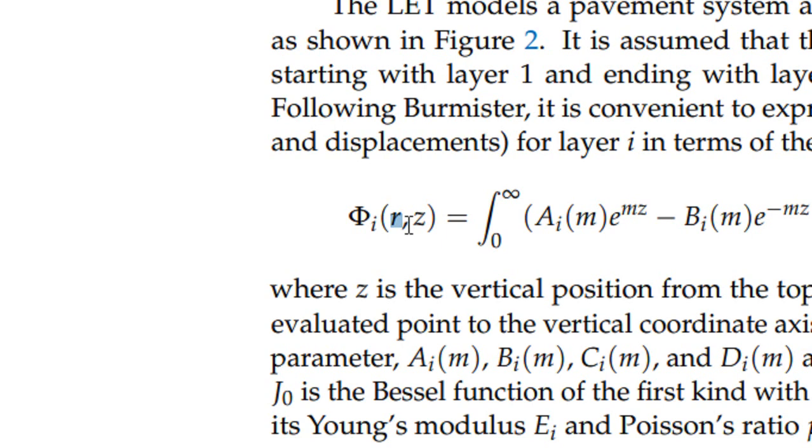But in reality, pavement extends far beyond the loaded area. So using infinite elements or viscous boundary conditions to simulate a semi-infinite space, or truncating the model with sufficient distance to minimize the boundary effects. This is the point which brings our focus toward the limitations of the LET concept.